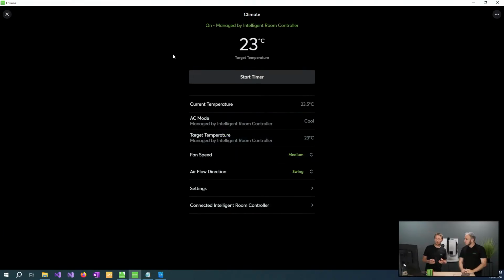We created a way that the AC control does not turn on or off too often. So if I'm in comfort mode, it only turns on as soon as I exceed my comfort temperature, because before that it's not necessary, and then it turns off when the comfort time ends. We did this because we don't want to disturb the homeowner by turning the AC unit on and off, and therefore we minimize the number of turn-ons and turn-offs.